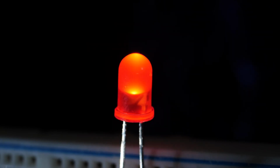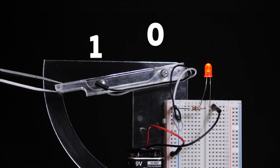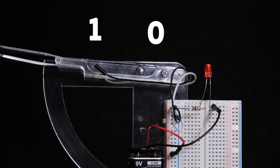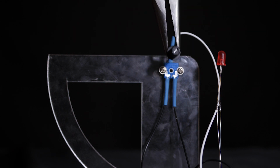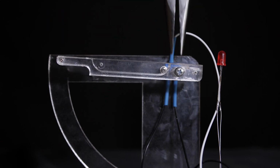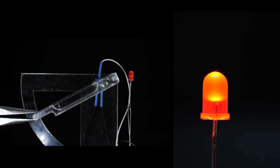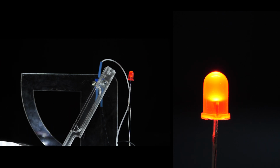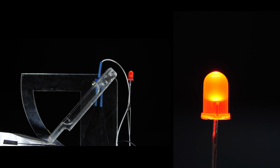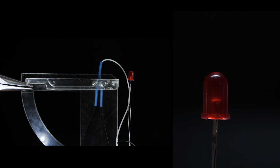Now let's put that to practice. Remember the digital signal of that ball on a rocker. No matter the angle, the LED would be either on or off. What if I put a potentiometer into that bench? I take the knob out and put in a rocker instead. Now we can not only switch the LED on or off, but also change its brightness. The potentiometer tracks the rocker's position and changes the voltage accordingly. The voltage changes gradually, and it is the main difference between analog and digital signals.